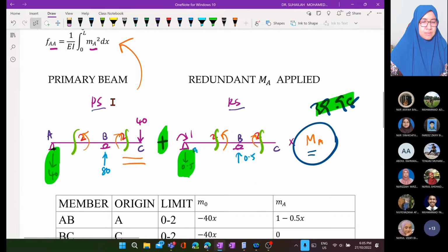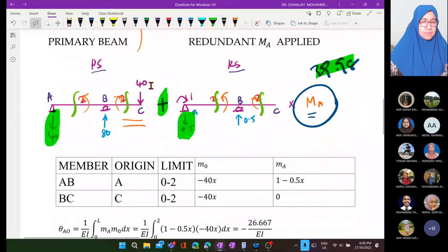So we analyze two determinate beams with the same support, section, limit and origin, except the loading is different. The primary beam keeps the external loading, and the redundant beam has all external loading removed and is subjected only to a unit value of redundant. For both systems we calculate the reaction and write the moment equation for beam and frame.